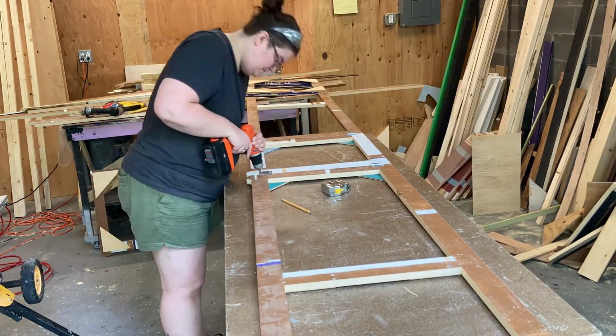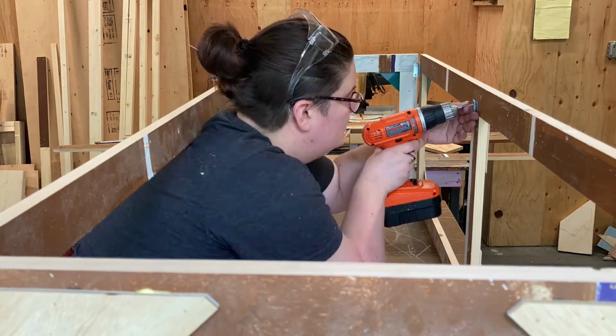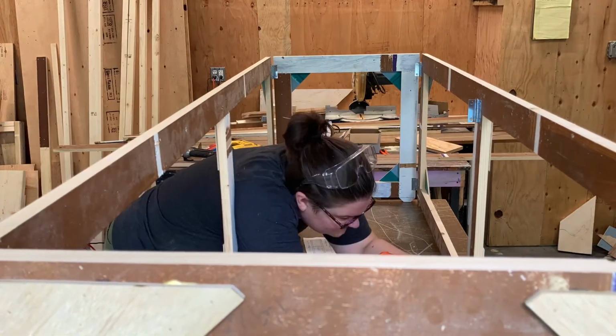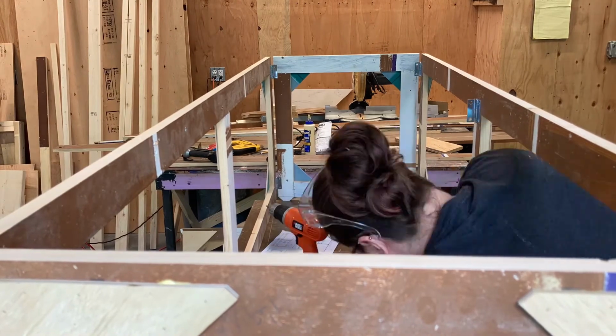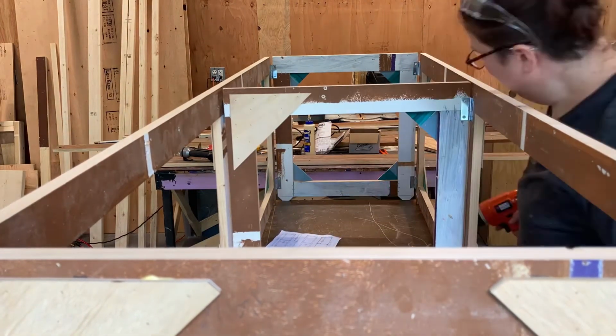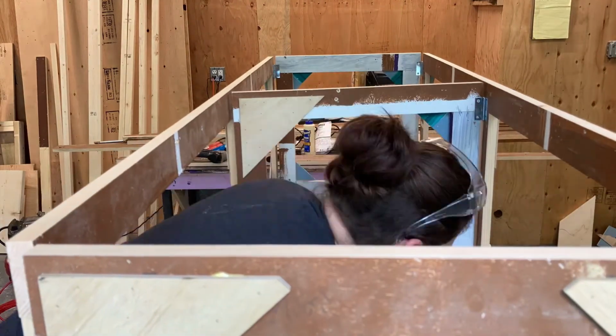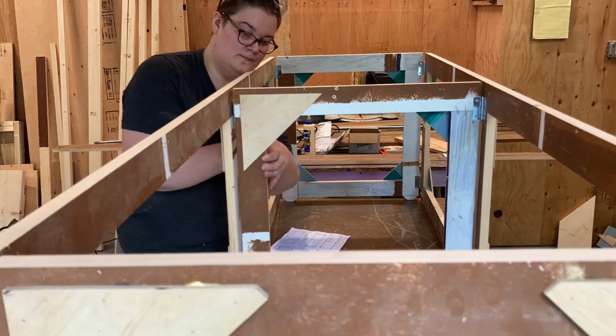Here, I'm very carefully aligning these hinges so that the gaps between frames are consistent. The center interior frame goes in at a slight angle, which allows the barrels of its hinges to be seated directly at the center of the unit. If this placement is too far off, the frame might bind when operated, or it may not collapse as tightly as intended.